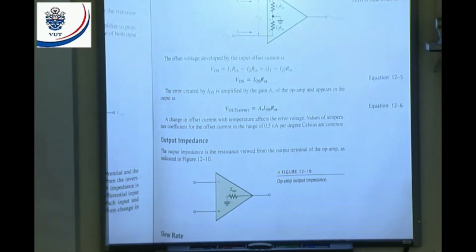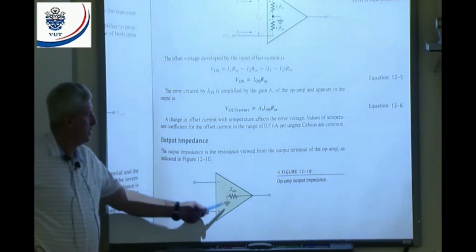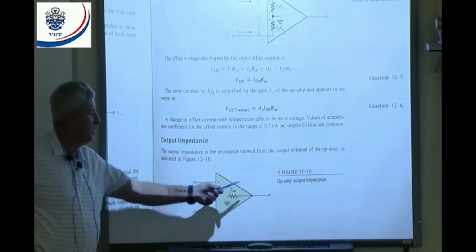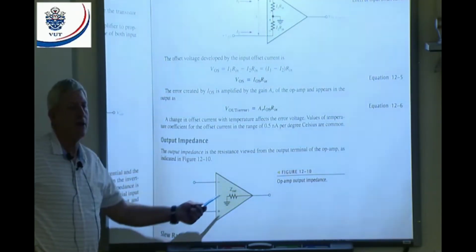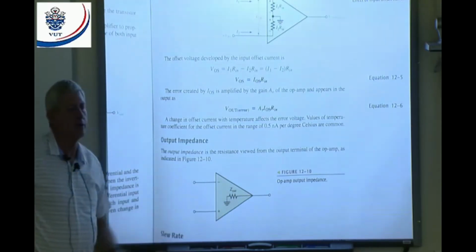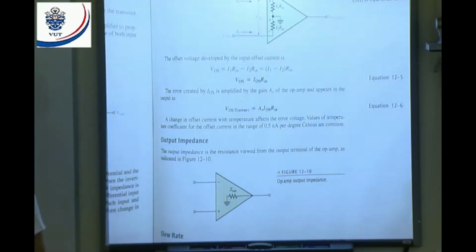We already talked about the output impedance. There you can see the output impedance. That means the moment I draw more current, the larger the current I draw, the larger the volt drop that will develop inside the device. Smaller current, less volt drop inside the device. All right. Everybody with me?